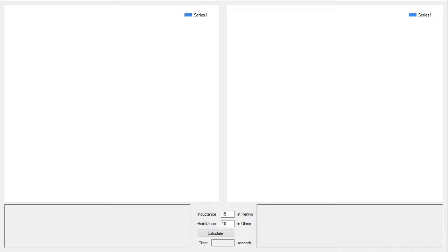When tau equals 1 we have a full cycle, if you like. That's 5 time constants. Now I have guessed incorrectly in the past the actual measurement for 5 time constants. According to most documentation it's actually 99.5. Now the number can vary a little bit depending on where you read, and what you read about it.